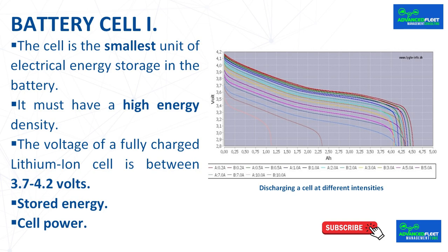Charging more than 4.2 volts per cell can cause stress on the cell, resulting in oxidation that reduces battery life and capacity, and lower voltages can increase battery charge cycles at the expense of shorter operating time.